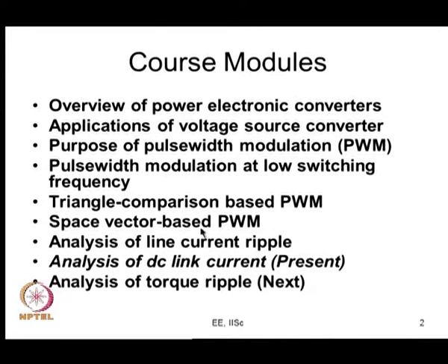These are two different options for how you go about generating the PWM waveforms. Whereas, we have a class of bus clamping PWM techniques which we call advanced bus clamping PWM methods, which require a space vector based approach for PWM generation.